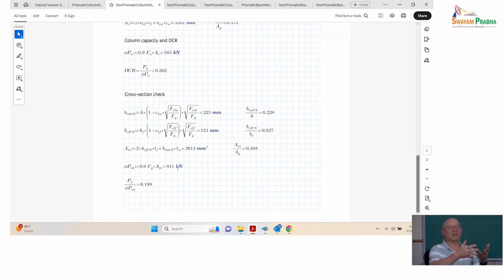Okay, let's do a cross section evaluation everywhere, and we'll identify the cross section in every member that has the largest P_u to phi P_ns, and we'll go there and just do one member check at that location, and we're going to take that as the critical cross section. It doesn't necessarily always land you on the one that would be the most critical, but it gives you a reasonable result. Even with this crazy cross section here, we're within like 0.03 of nailing the 0.262 at the top.